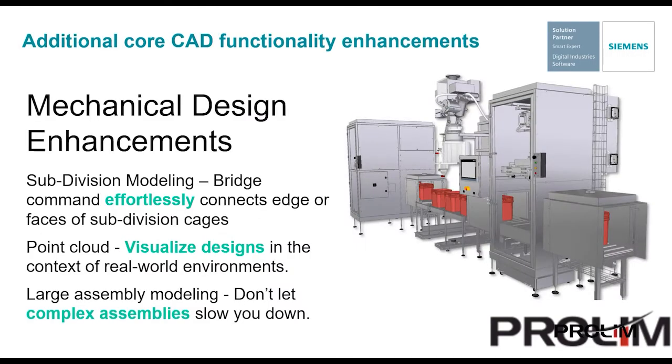So enhancements to the subdivision modeling are really groundbreaking. Subdivision modeling is already a really cool feature within Solid Edge, but the new bridge command effortlessly connects edges or faces or subdivision cages and creates a lofted structure between them. The curve can also be used to help control the overall shape.